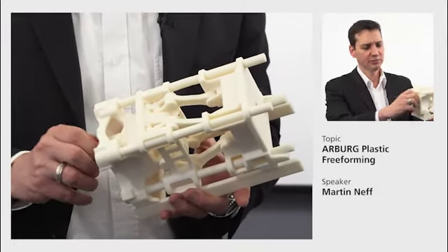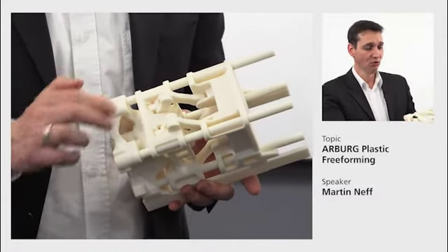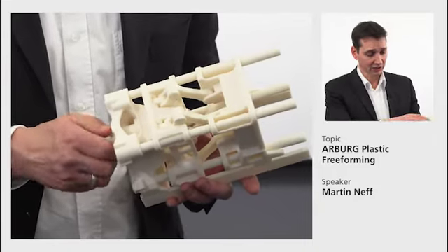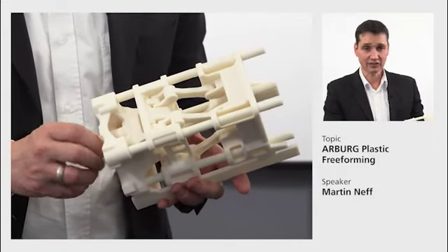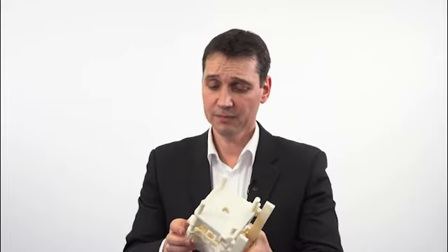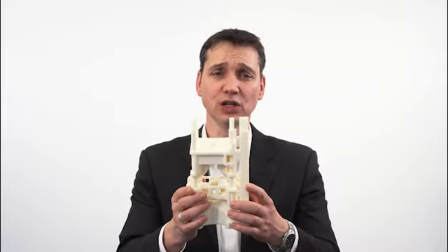By rotating here, there is a spindle inside, you can actually move those toggle joints. We are talking about over 20 individual parts which were built in one print job. And for that print job, we have 10 to the power of 8 droplets. That means over 100 million droplets.